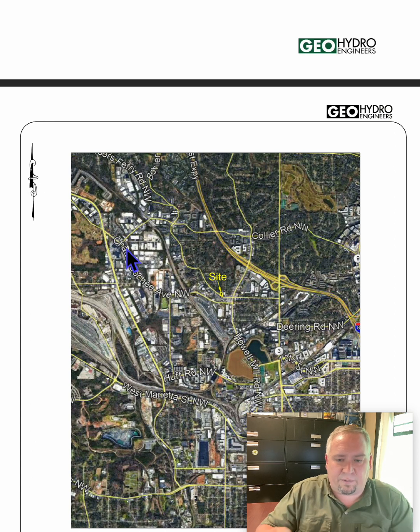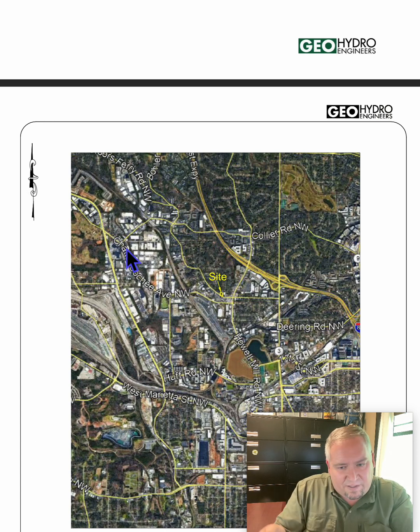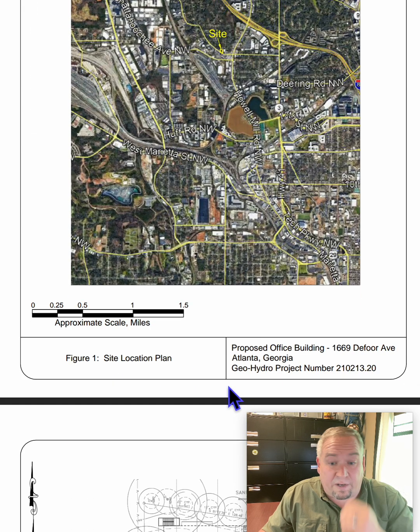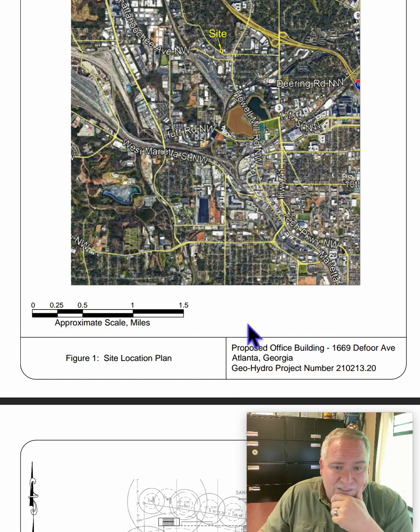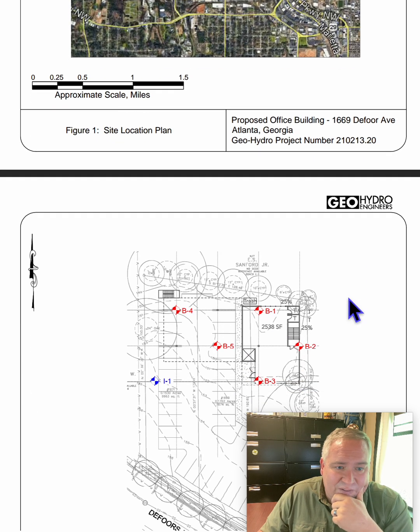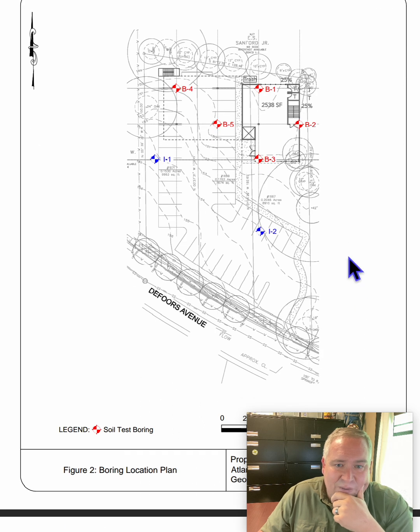So the first page here, we've got our north here. So when we get out there, we can actually adjust the plan and get ourselves positioned and know exactly what we're dealing with. We've got our scale. You want to verify from whoever printed this thing that the scale matches. So do a scale verification. Let's make sure that the address is correct. Everything's good there.